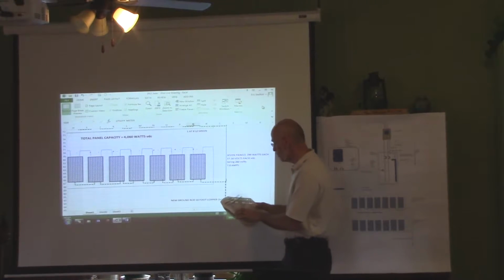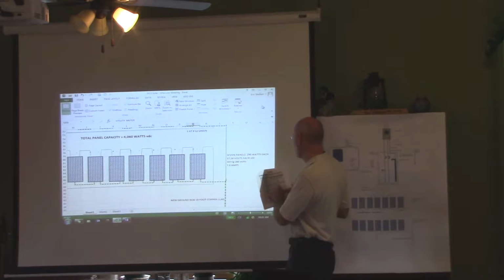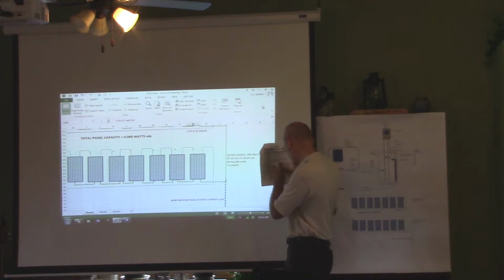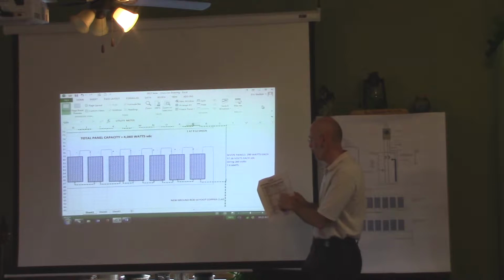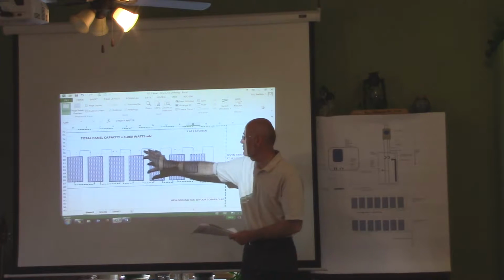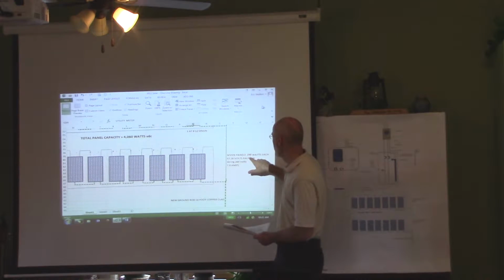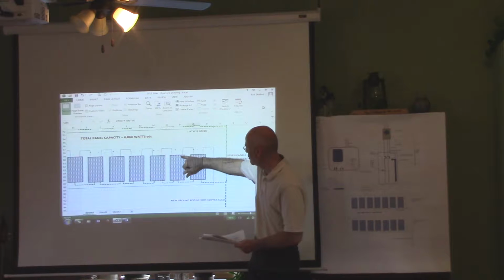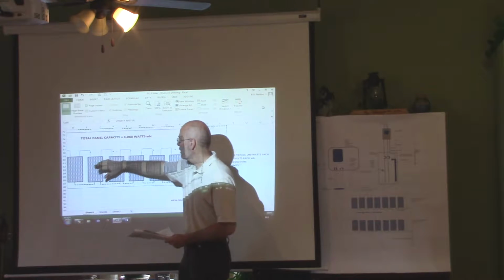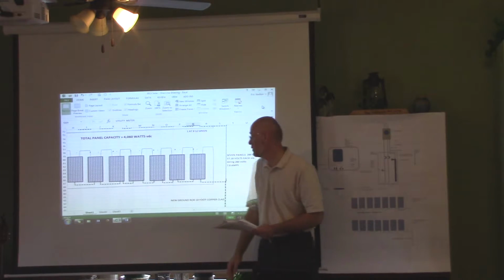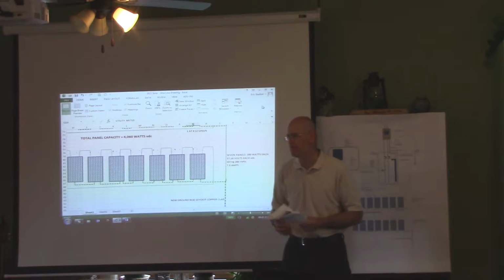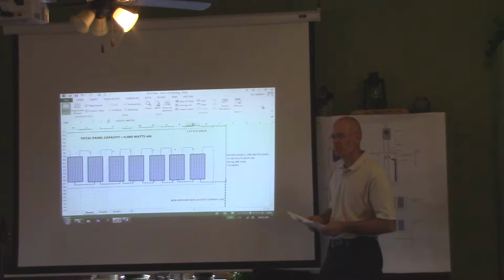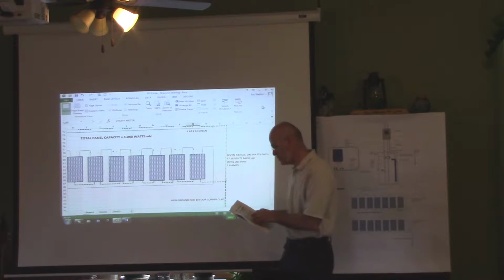Similarly, when we go to the specifications on this data sheet, you'll see the normal operating range DC, 230 to 500 volts. So we need to put our solar panels in series to get up to that voltage. So 37 volts, and I come off the positive, go to the negative, come off the positive, go to the negative, come off the positive. We do that, you should have 7 panels here in series. So 7 times 37 is what? Who can do that real quick? 259, okay.